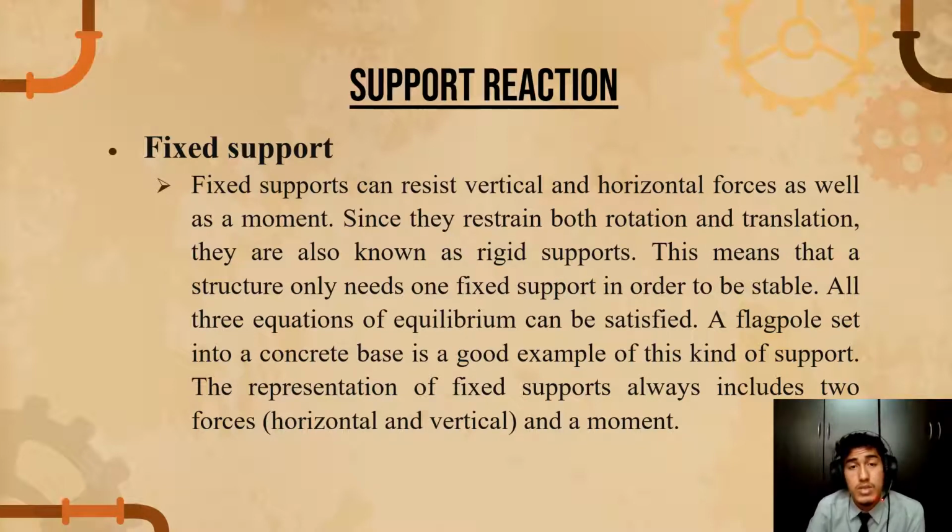A flat post set into a concrete base is a good example of this kind of support. The representation of a fixed support always includes two forces, horizontal force and vertical force, and a moment.